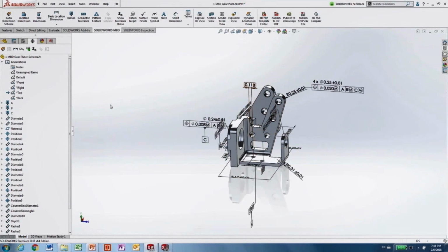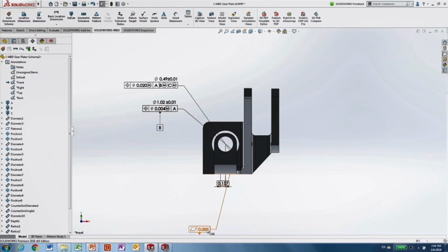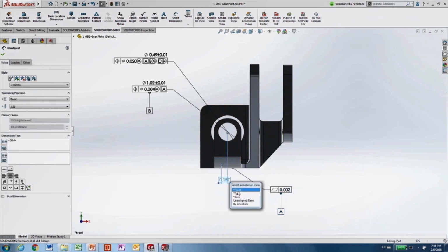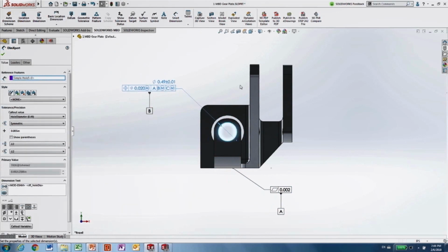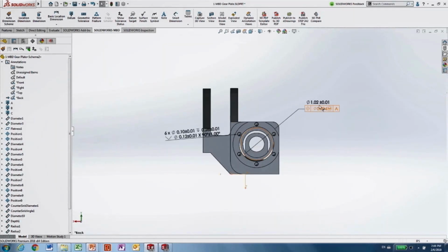I'm getting pretty close to the point where I have all the information I need. What I can start doing now is go through the different views I have and, as I mentioned, reorganize things nicely. Once I'm done with this, I can create my 3D views that will help me navigate through my design. Those 3D views that we saw at the beginning, I'm going to create a couple more of those. They will be not only in the SolidWorks file for me to look at, but I can also export them to a 3D PDF, an eDrawings file, and so on.